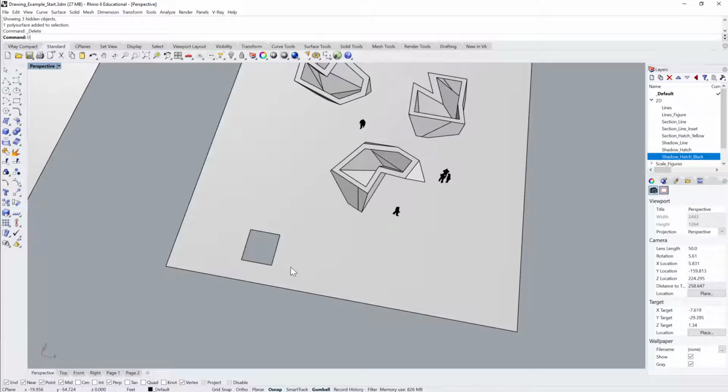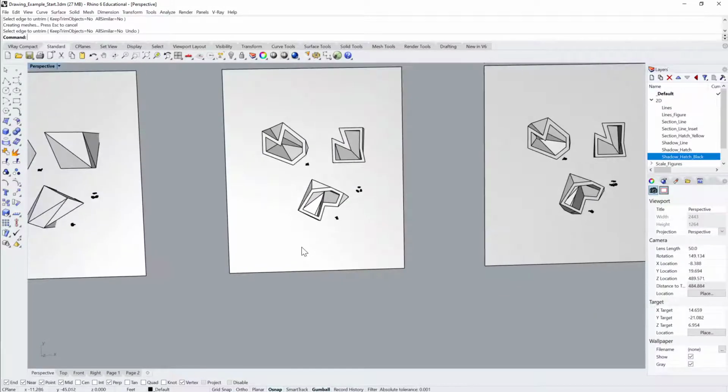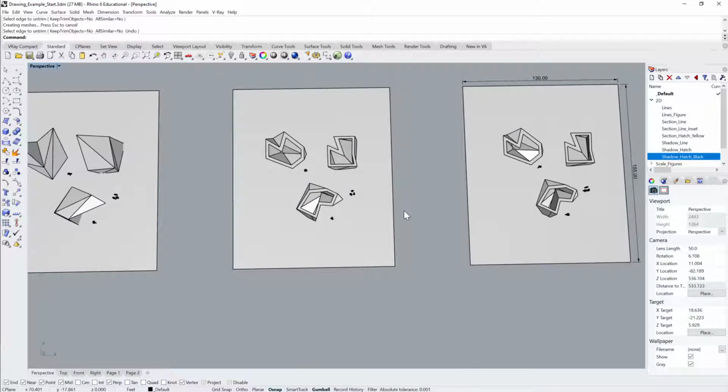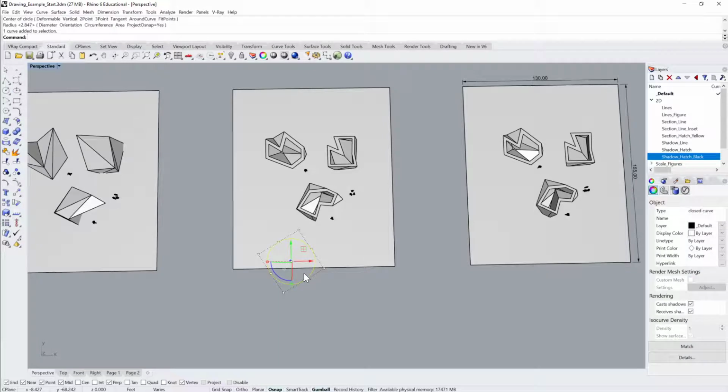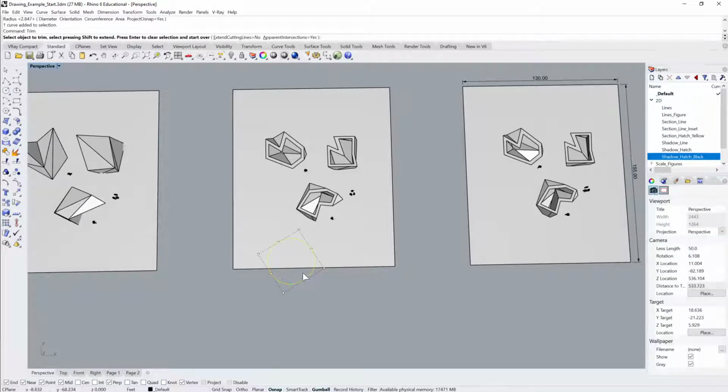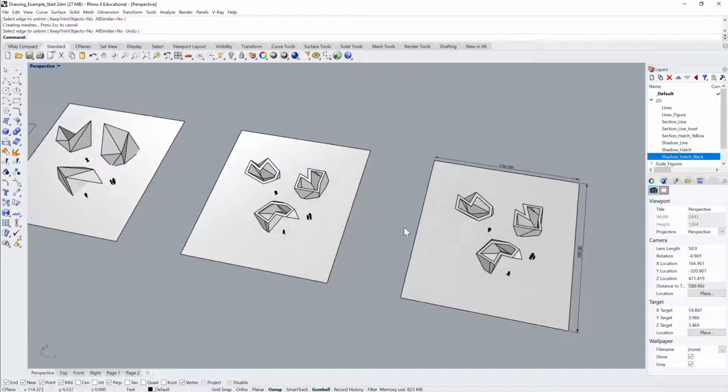So, by the way, if you ever want to get rid of a hole on a NURB surface, all you have to do is untrim, click that, and boom, it's gone, right? In Rhino, when you trim a NURB surface, you're only ever just masking it. So whenever I do something like that, trim, if I turn the points on for this surface, F10, the surface is still there. If I want to show it, all I need to do is untrim. Okay, cool.